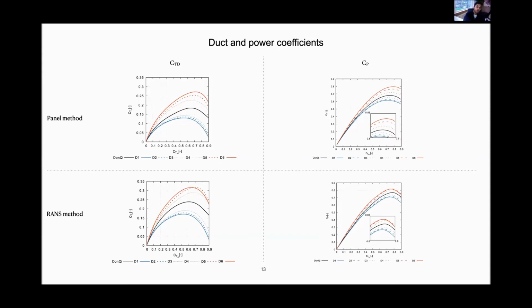On the x-axis, we have the different loading of the actuator disc, simply saying, different rotor loadings. And on the y-axis is the duct thrust force coefficient. What you would observe on the right figure is a slight overlapping in the trend lines on the bottom figures, and this is due to the viscous effect.